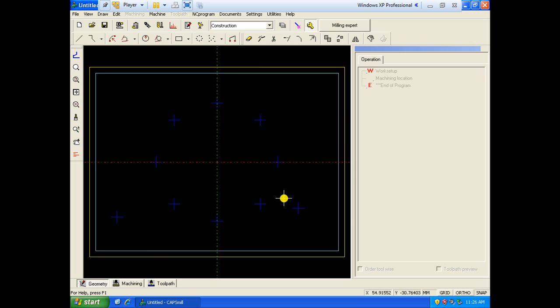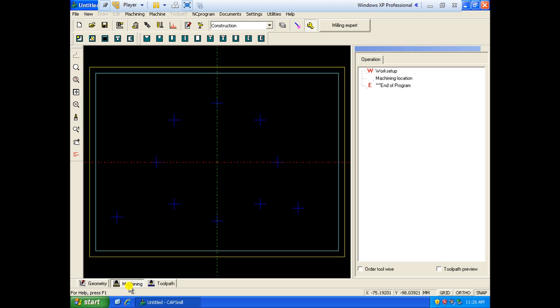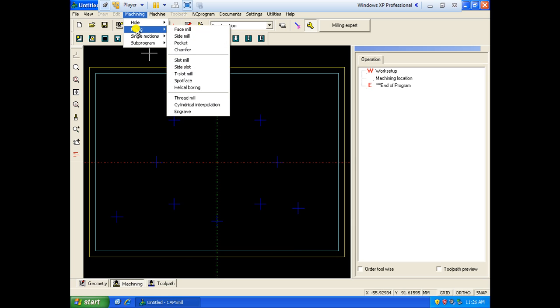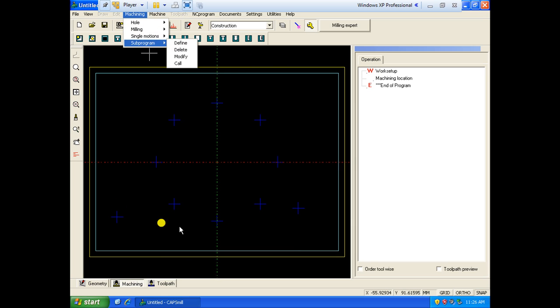Here the part definition is not required, only the blank is defined. We have completed everything, the geometry is created, and the blank is also defined. Next, after the completion of the geometry, is the machining mode. Go for machining. The first operation, under this, is to make the face: we need to finish the face, or machine the top face of this completely.